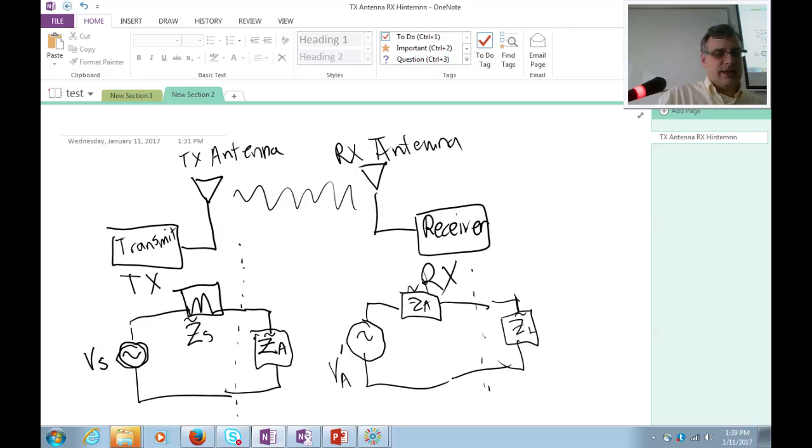The other consequence is that the impedance that it presents to the circuits is the same. These are the same if they're the same antenna at the same frequency. That's nice, because basically if you go up to a network analyzer, connect an antenna to it, and sweep the S11, that is, you're looking at the reflection coefficient, you're exciting the antenna and seeing how much power reflects back, and that traces out what the impedance is, Z sub A. If you do that, you're using the antenna effectively as a transmitter.